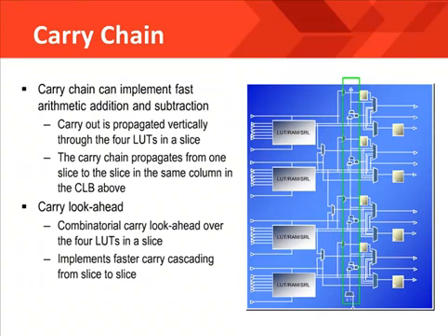Carry logic is a dedicated hardware resource that improves the speed of arithmetic functions, such as adders, accumulators, subtractors, and comparators. From the diagram, you can see that the slices are grouped into one carry chain. Please note that carry logic will propagate the carry signal vertically upward. This is important to note because most designs use carry logic extensively, and by using it, the least significant bit should be placed at the bottom of the carry chain. Likewise, when carry logic is used, bit ordering should be followed by the designer, with the less significant bit being placed beneath the more significant bits.